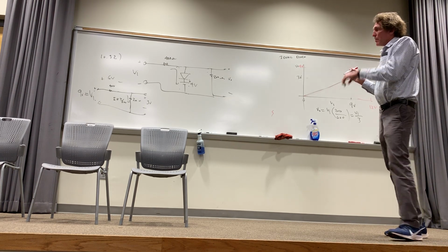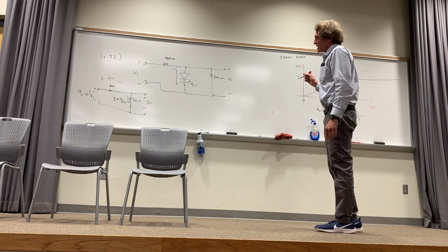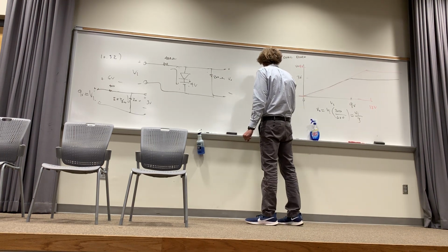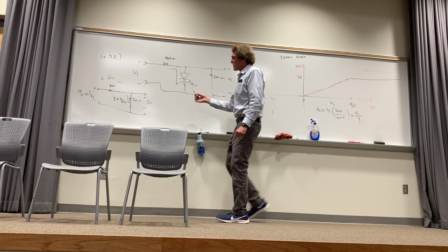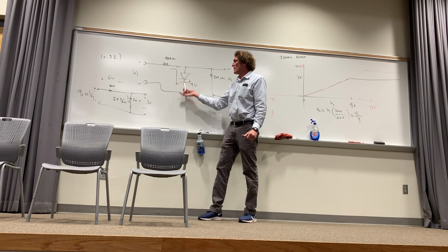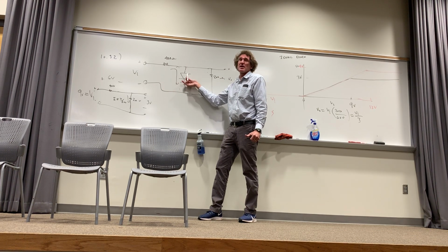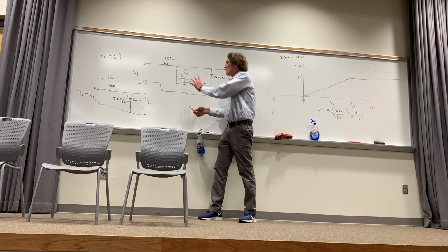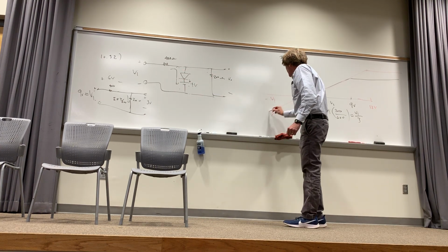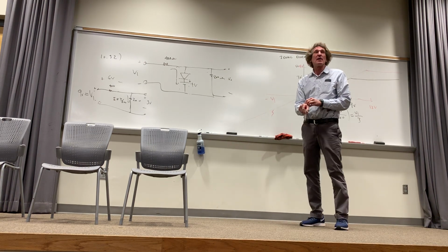Now, for the negative values of voltage, I just want you to try to go with me on this. If I talk about minus here, I'm going to have this becoming positive, and I'm trying to drive current this way. Now, what do you know about this? If you try to drive current this way, what happens? Can any go? This looks like an open circuit. So whenever there are negative voltages here, the output is just 1/3 the input, straight down there. Got that, class? Because the diode has no bearing on that.